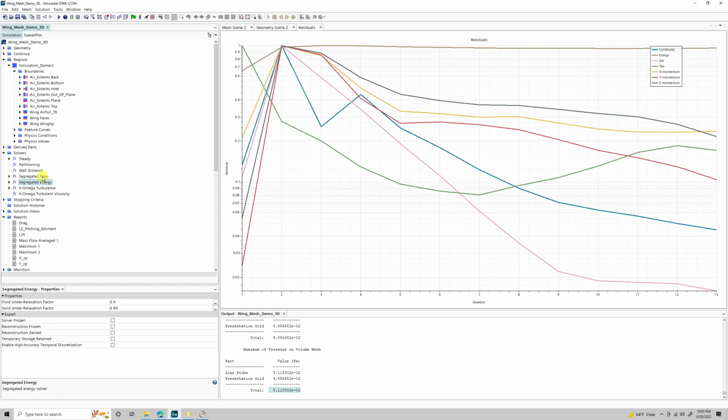So for flow, which is continuity and momentum, for energy, and for turbulence, which is its own separate thing, each can retain its own temporary storage. I'm going to have this iterate once, because right now it's already thrown out those values. For iteration 13, the iteration we're on, it already calculated the residuals, added them together, normalized them, and threw out the per cell values. If we want per cell values, we need to make it calculate them again. It means running one iteration. So, I'm telling it to run one iteration, and we'll give it a minute.